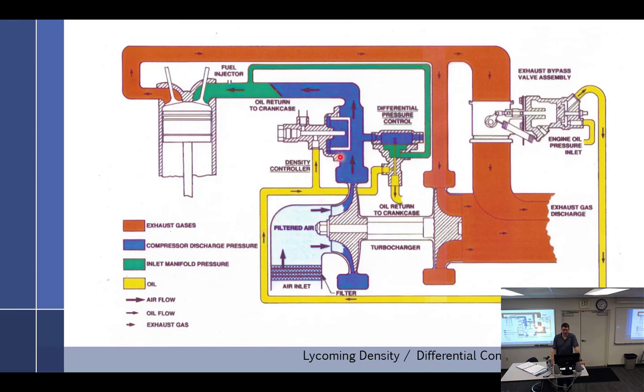So we open up the throttle. I just opened it. Well, now that opened up, and so the differential pressure controller says, you need some more, you don't have enough differential. We've got to close off. So that closes off. You've got to wait for the oil to back up and start pushing on this piston. It's going to take time for that piston to move and move that throttle plate, right?